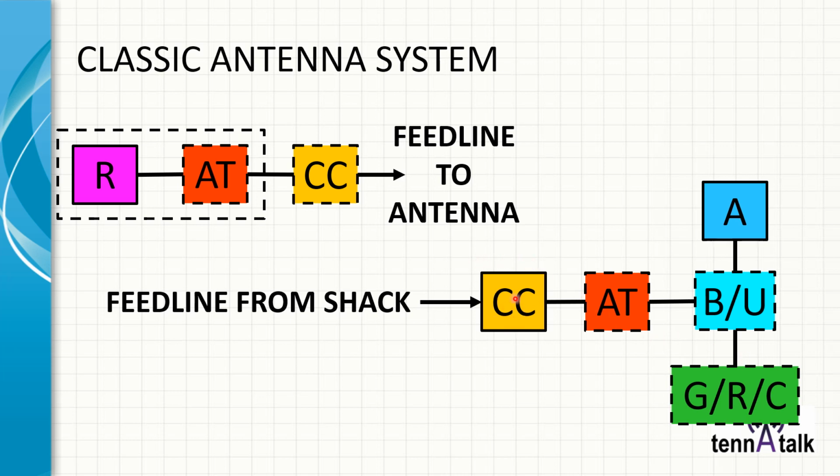Talking about the current choke, there's several current chokes, and we'll get into it in future podcasts, but why would this be more mandatory at the antenna than at the shack end? Well, what this does is it isolates your entire antenna past that point on the antenna side of the feed line from becoming part of the antenna all the way back to the shack. So think of it as an antenna isolator, and sometimes it's actually called an isolator. Sometimes it's called a one-to-one balun.